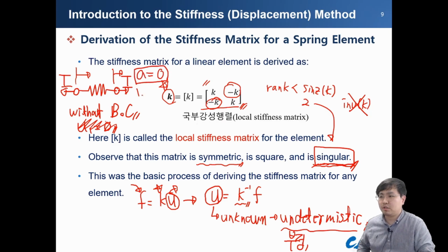However, consider their initial velocity. Can you say that this spring element is in a stopped condition? I mean that the velocity is always equal to 0, so we cannot say that. Without boundary conditions, this spring element can translate. So the total displacements u1 and u2, we cannot say them to be specific values. Maybe u1 becomes some v0 t.